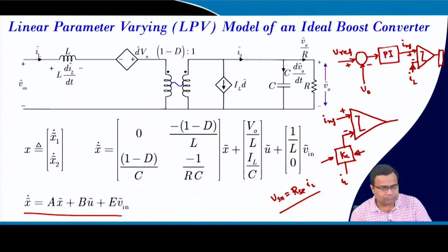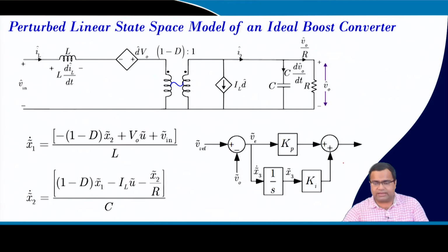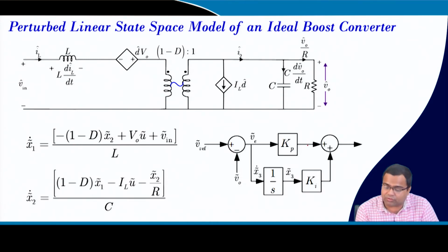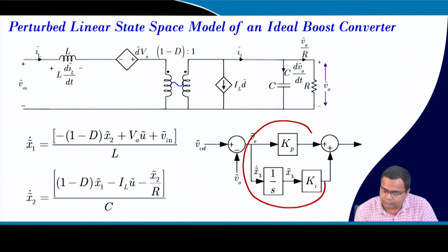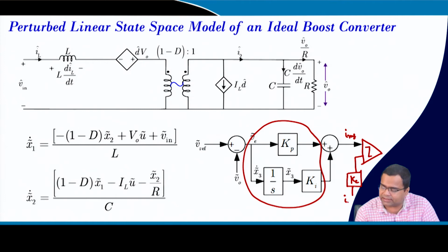So, in state feedback control, what we did, we have considered this PI controller separately, we have just modeled it, and this is a very well known augmented model. This is my reference current, compared with, I would say there is a gain Kc, and that is my actual inductor current, and if we take tilde perturbation, this is compared, right, and this is going to the modulator.